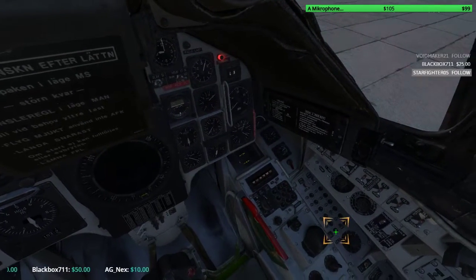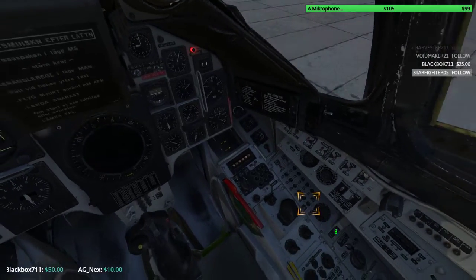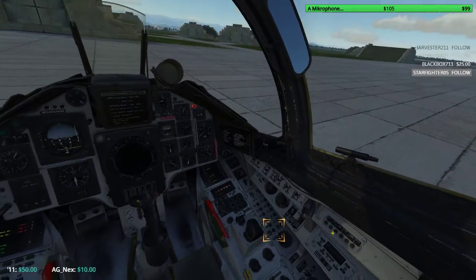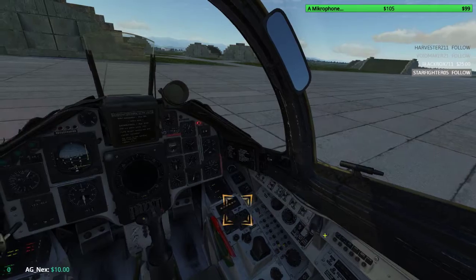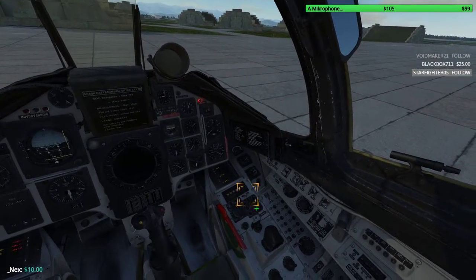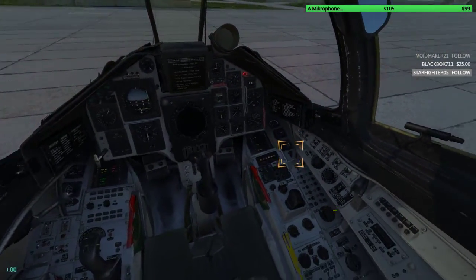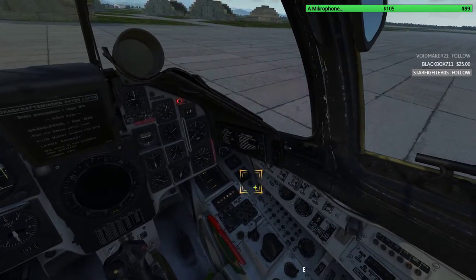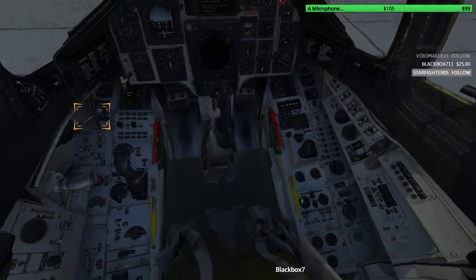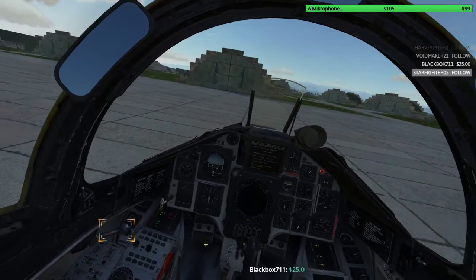Press the LS waypoint button to enter. The first digit 9 will flash until the transfer is complete. Set the input-output switch to out. Open the oxygen valve by moving the lever forward. Close the canopy by pushing the canopy lever forward.